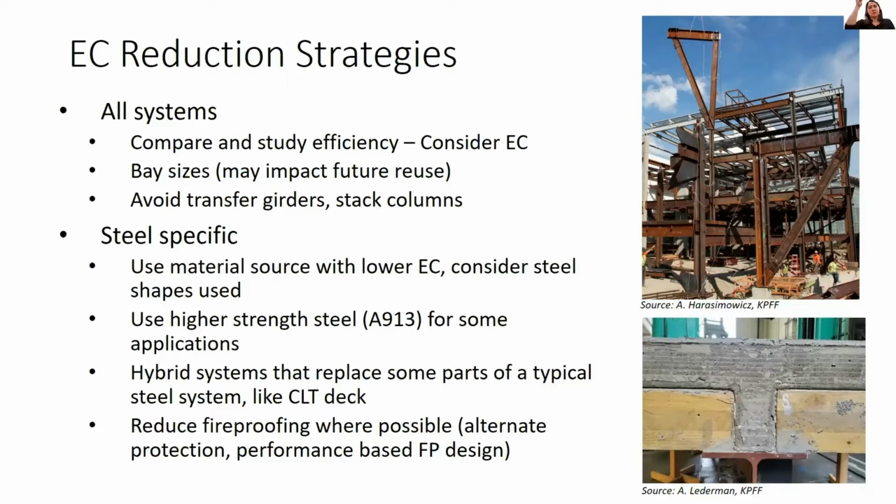If the best path once you get a load to a column is to go straight down to the foundation. If you have to take that load and transfer it horizontally, then you oftentimes have to use very deep, inefficient sections to get it someplace else. So those are the all-systems strategies that you can use.